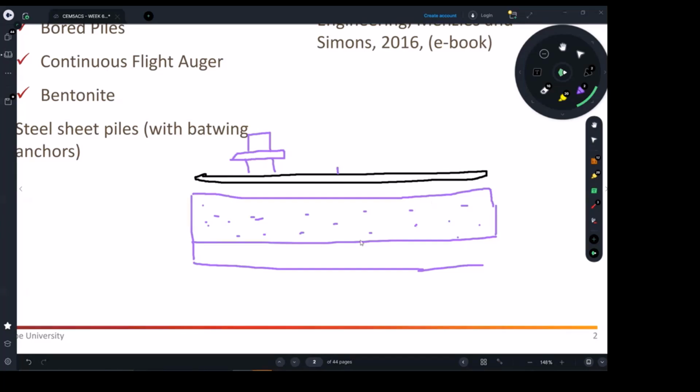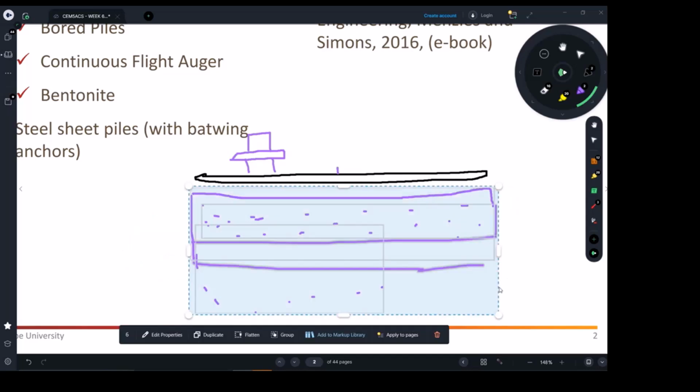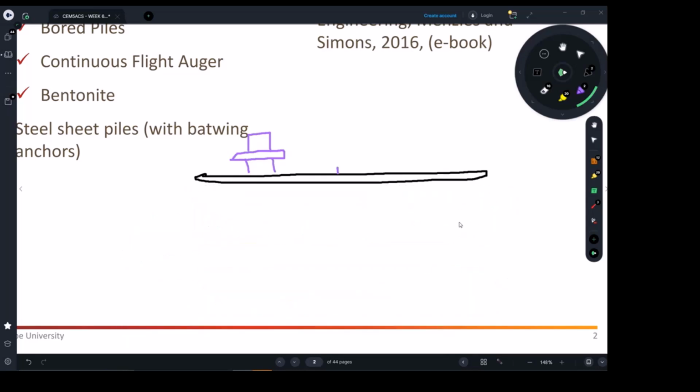So what they do sometimes, or many times, especially in the region of Melbourne, is you may have maybe 2 kilometers of very soft ground. Maybe there is some ground movement or whatever. You don't know what's really behind it. It's more to do with geotechnical engineers. They found there is a section which is all fill. It goes for maybe 5 to 10 meters, whatever, and the road will just keep sagging, which won't be acceptable.